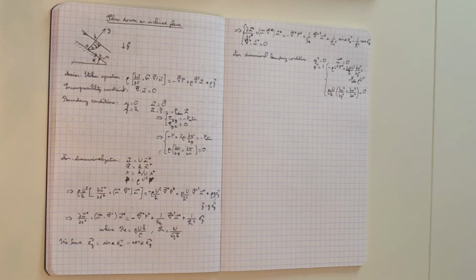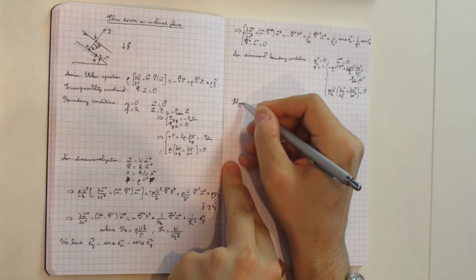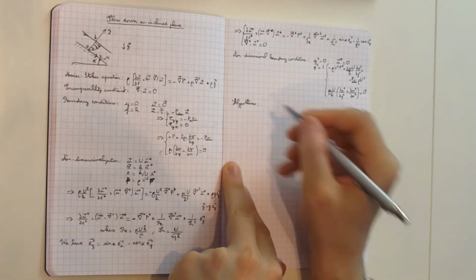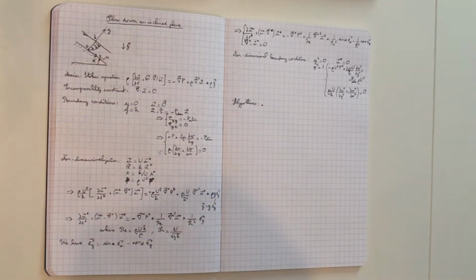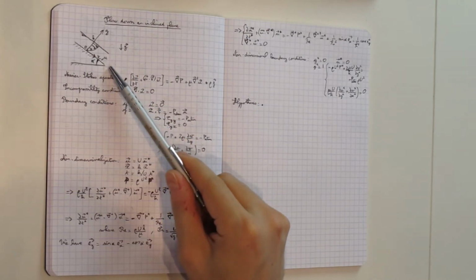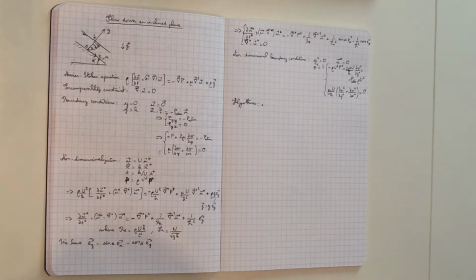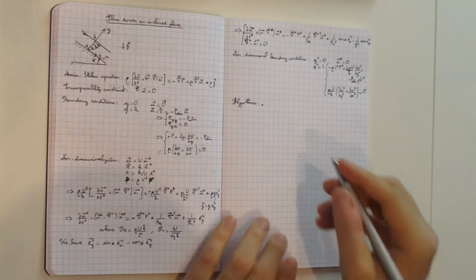this is our system, with our non-dimensional boundary conditions. And before we solve for it, we just need to make some hypotheses about the flow that we're looking at. So hypotheses. And these hypotheses are here to guide us into finding the simplest flow realization that can be supported by this configuration. This is a nonlinear problem, so we don't want to solve for all possible cases. Most of them are actually intractable analytically, but we just want to find the simplest flow, like we could do for plane Poiseuille flow or plane Couette flow or other simple flow configurations.